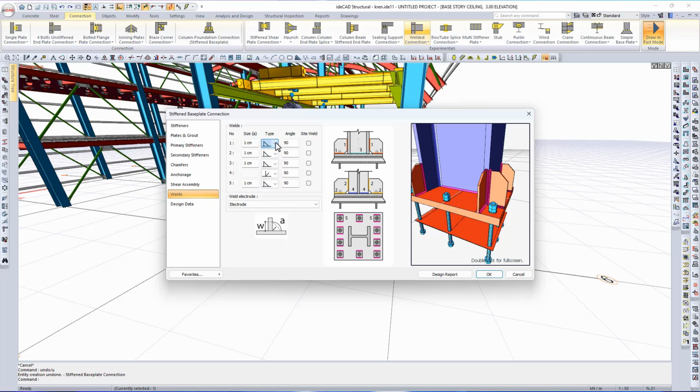By default, welding is considered for shop fabrication drawings. Welded elements are grouped as assemblies and fabricated in the workshop. However, if welding is required to be performed on-site, you should activate the Site Weld option by ticking the checkbox on the right.